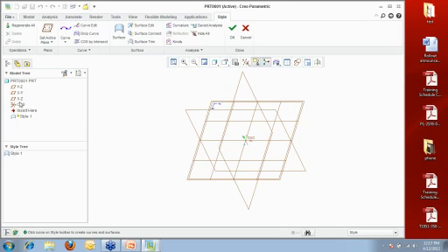Now, another part that makes the interface kind of unique is that once you get into your ISDX button, what you have is your current model tree, which has all of your parametric features, and then you have your style tree. Now, really what makes this unique is that I'm creating multiple style features, or ISDX features, within one feature, one ISDX feature, so it doesn't matter when I create them.